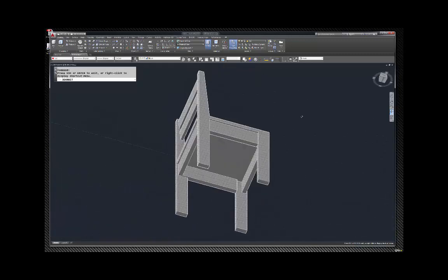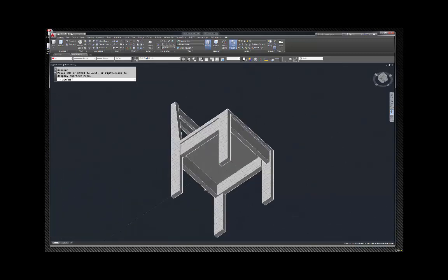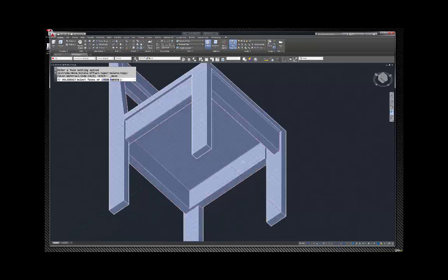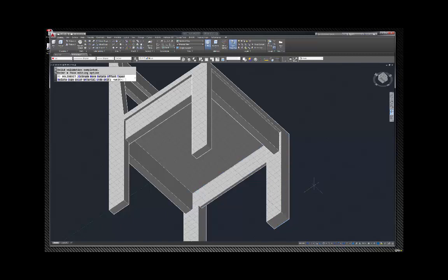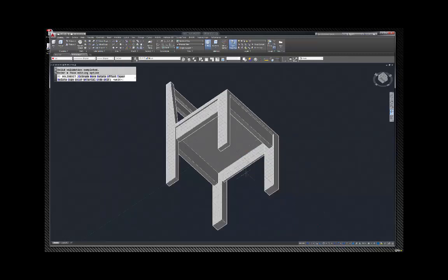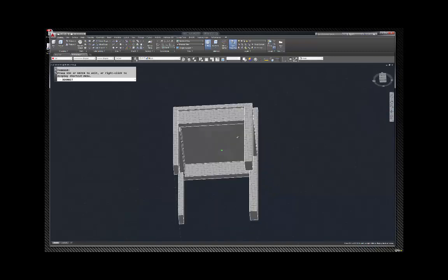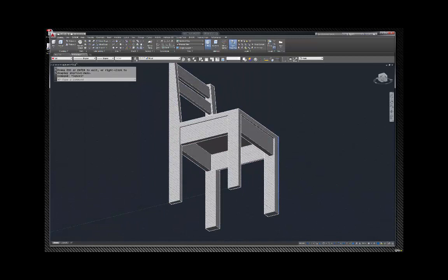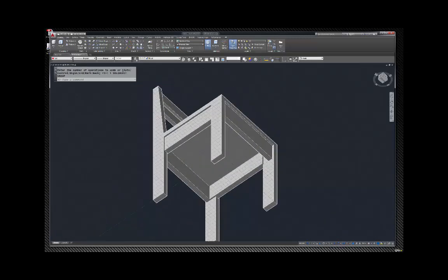Looks like these ones on the side, notice that they're sticking out. Okay. So I'm going to grab that plane, and I'm going to go to my friend over here, move face, and see if I can grab this face here. There it is. And move it back 0.5. Awesome. Okay. Let's see if that did anything to the outside here. Make sure I didn't screw it. Oh, it didn't like that at all. So we're going to just not do that. We're going to undo that then. Undo, undo. There we go. We'll just leave it for right now.